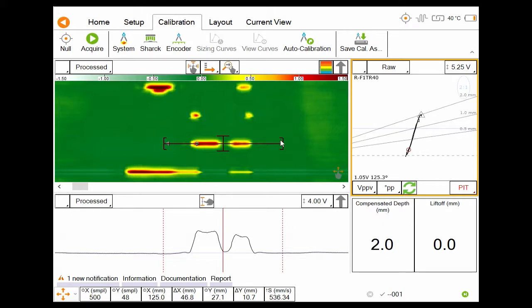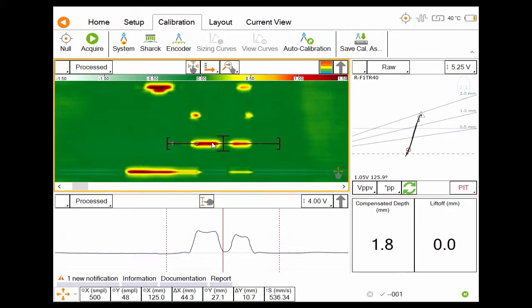So in that case here, we added two defects very close, one from each other. I think that the distance between these defects was about 3 millimeters. If we look at the strip chart below, we can see that the operating point just moved up because we were on the first defect, and we reached back the null mark here before detecting the other defect. So that means that in terms of axial resolution, we could distinguish defects which could be closer than this one.